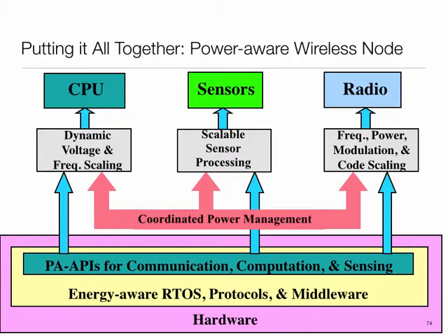So the solutions to those, I kind of briefly alluded to thus far. One is that the sleeping radio can periodically wake up and say, aha, are you trying to wake me up? And kind of listen for that. Or the alternative is I can have a very low power secondary radio, which is always up, and I can use that to wake up. And that's the concept of the paging radio or the wake up radio. So those things are kind of around as well.